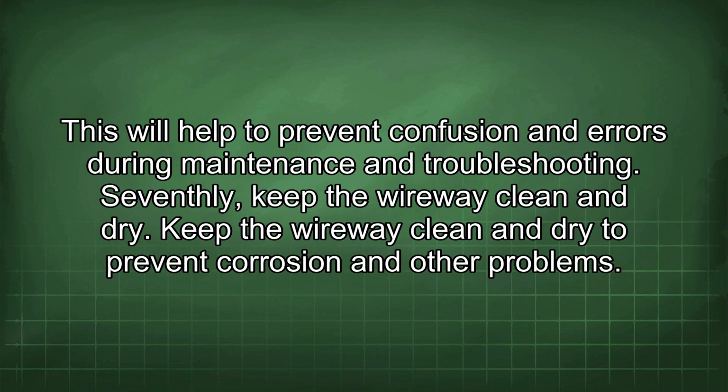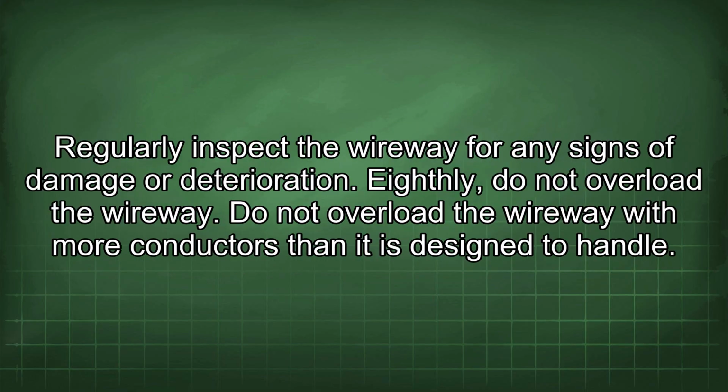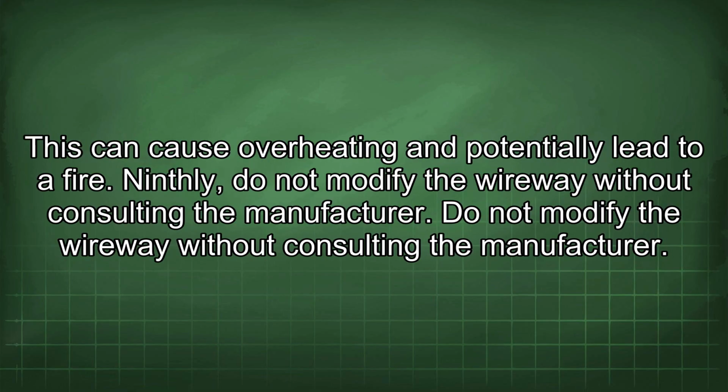Seventhly, keep the wireway clean and dry. Keep the wireway clean and dry to prevent corrosion and other problems. Regularly inspect the wireway for any signs of damage or deterioration. Eighthly, do not overload the wireway. Do not overload the wireway with more conductors than it is designed to handle. This can cause overheating and potentially lead to a fire.